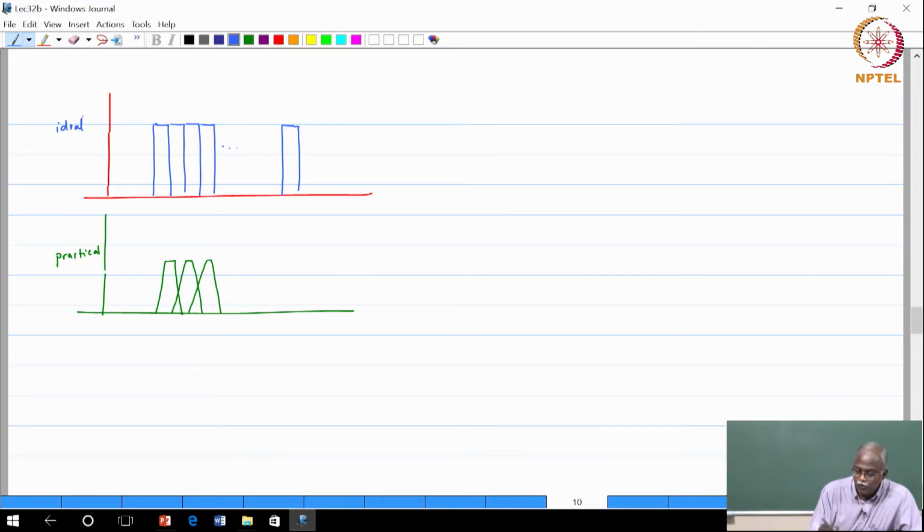Now, we know that even if the 2 waveforms are overlapping in frequency, there are certain conditions that you can impose on them to maintain orthogonality. So, therefore, we can generate orthogonality, but this is very important. A way to think of OFDM is, first of all, it is some form of transmultiplexing.